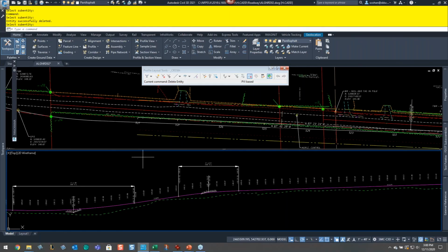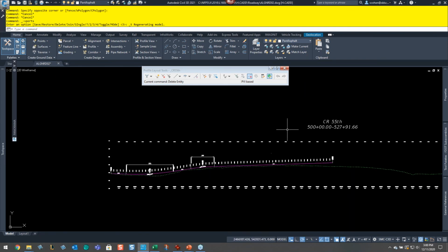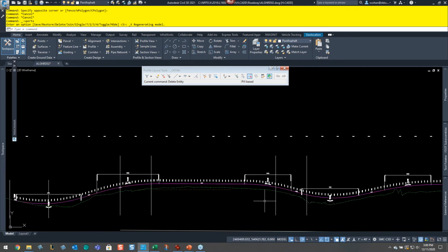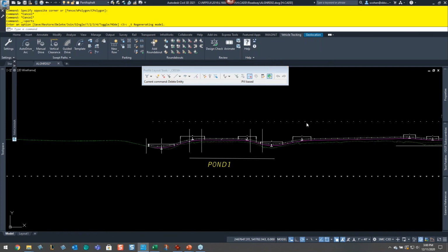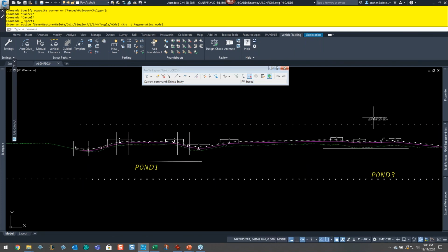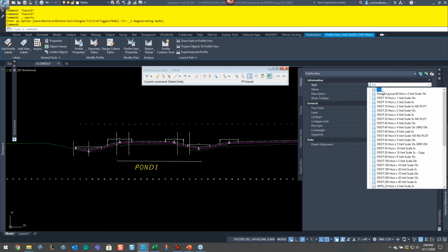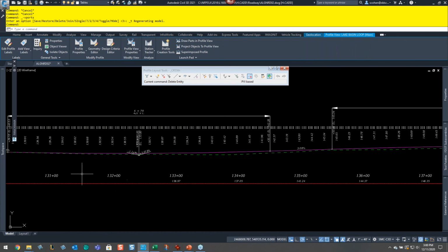Actually, yes. So that's actually a nice little tool here. Basically, if you want to make sure that you have a truck, let's say, can a truck actually fit along this alignment? I'm going to do it to this one here because I already have a complete profile. And this actually involves vehicle tracking. So if you have the AEC collection, you have vehicle tracking here. The one thing that this requires is that you set your profile view, which I should already have here, to a 1-to-1 profile. All right, so we'll just do 1-to-1 here, okay?